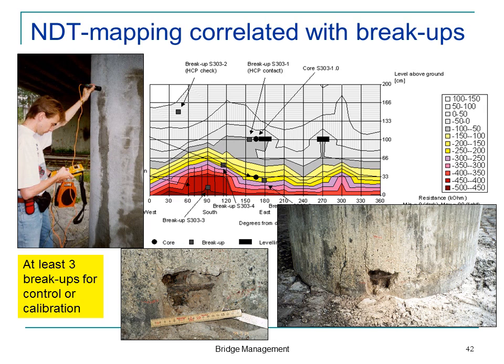What we, for instance, would do there would be make an NDT mapping. We create a map of, say, this round column, unrolled so we see 360 degrees on the map. And then we can make a mapping of, say, resistance in the concrete cover. Why that? Well, because the more water we have in, the lower the resistance. And we would say, hey, there seems to be an area down here with very low resistance. Yeah, that's not surprising. The concrete looked like this. It's very porous, it's very cracked.